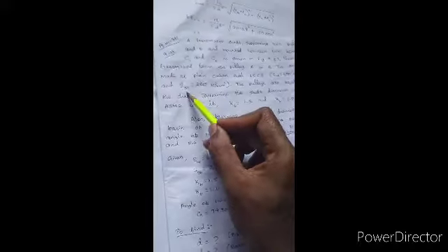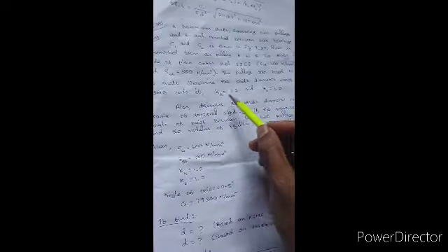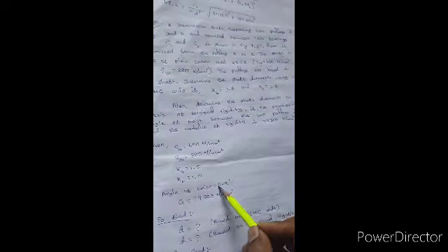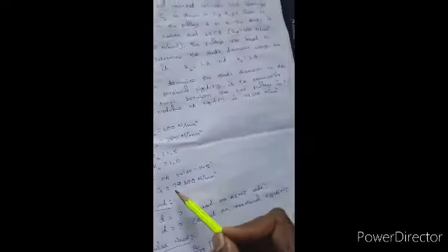Now let us extract the given data and write it down. First, what data are given? Ultimate tensile stress is 600 Newton per mm square. Write it down. Then yield tensile stress 380 Newton per mm square. Then the fluctuating factors KB 1.5, KT is 1. Write those things here. Then angle of twist 0.5 degree. Then rigidity modulus 79,300.